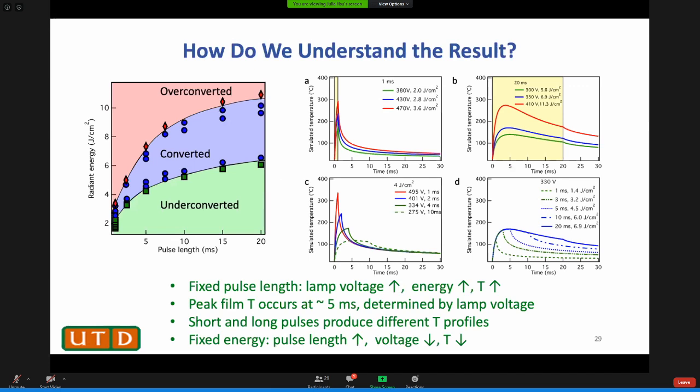When we increase the energy, the grain size gets bigger, compared to the thermal anneal one. However, at high energy, we see this extra particle. Those are lead iodide, and you can see them in the XRD as well. So more energy will get you bigger grain size.